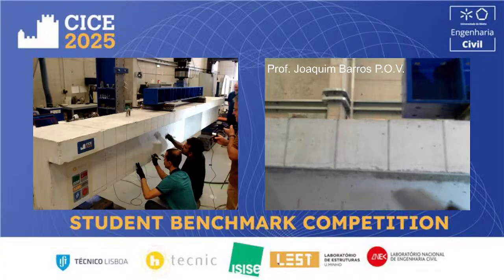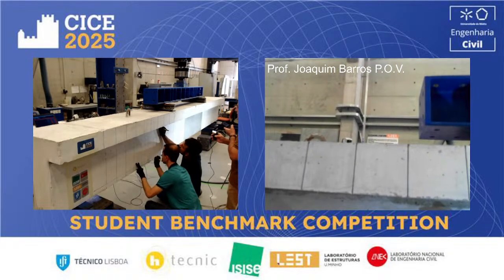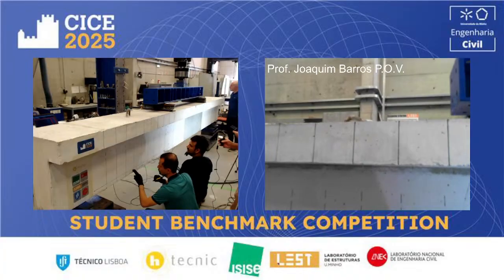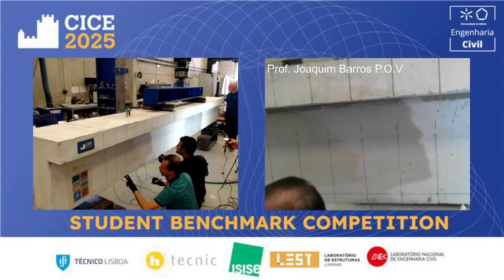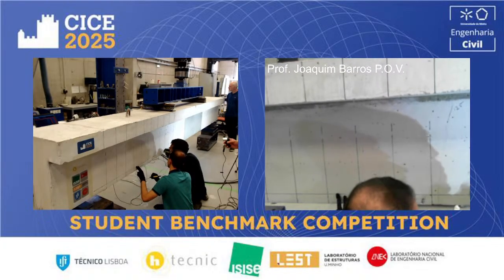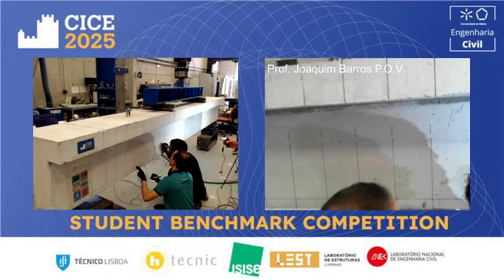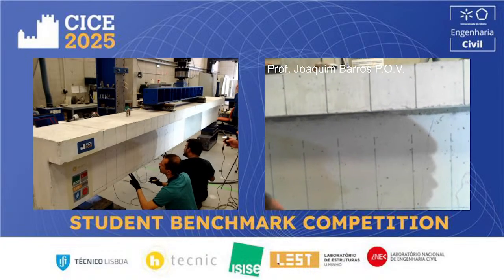Load 125. So now more cracks are being formed in the shear zone, in the shear span, but they are still vertical. 130 kilonewtons.